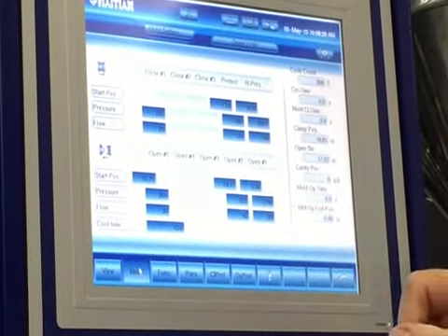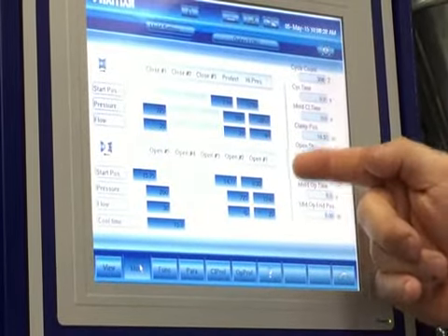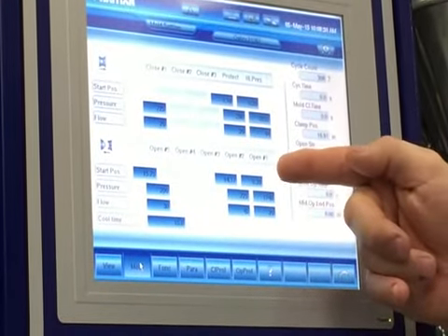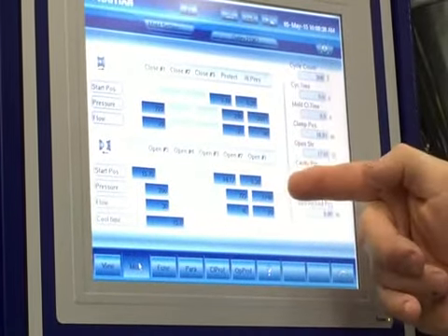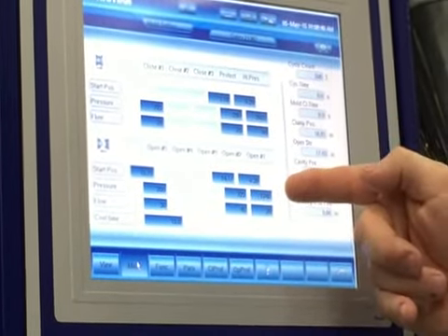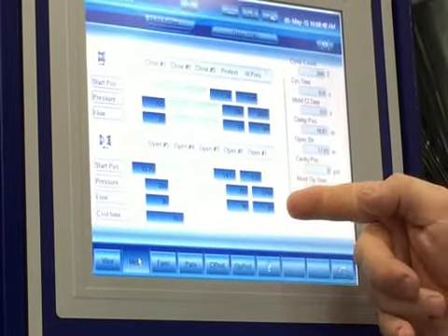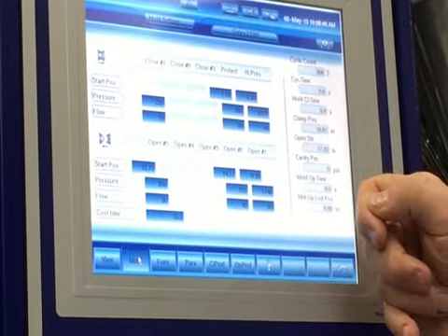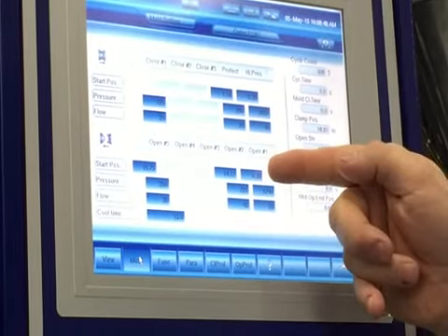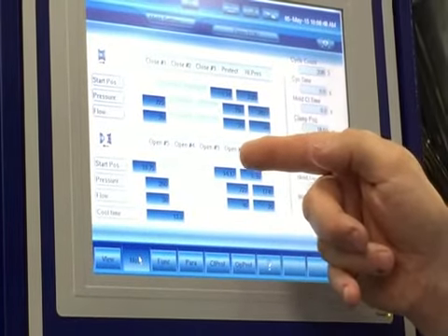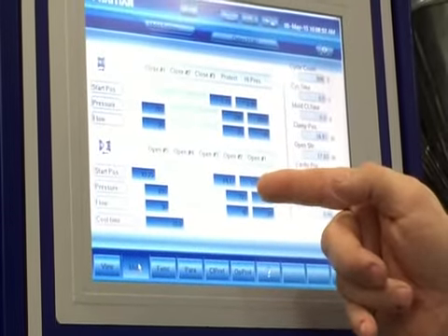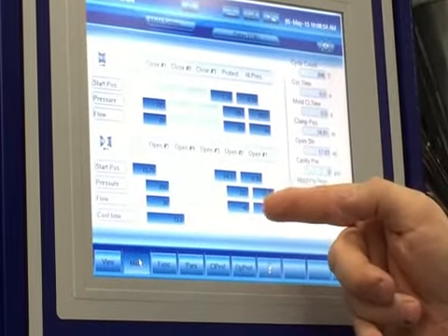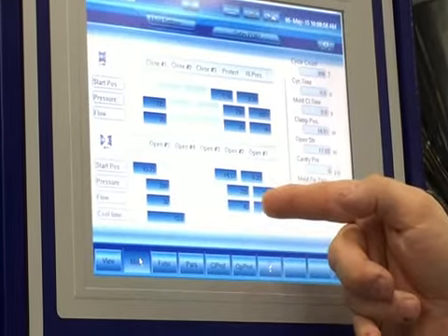Once we go into the open stroke, we're going to go from 0 to 0.39, which we know is breakaway, at 1,740 psi and 20%. From 0.39 to 14.17, we're going to go 725 psi and 45% flow.